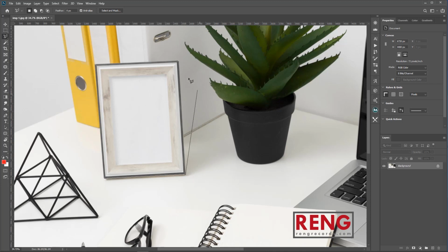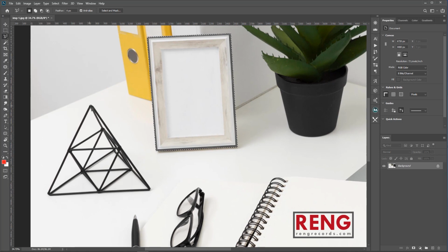Now move the mouse to draw around the desired area. In this case, a straight line will be drawn. To change direction, you can click the left mouse button to create a point. Number 4. To complete the selection, you can double-click the left mouse button. With this, the start is attached to the end point and the polygonal area is selected.